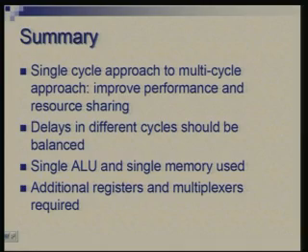So, finally, just to close, we had a design where the data path is conceptually simple in terms of the key resources, just one ALU, one memory and one register file, but there are registers and multiplexers which glue these all together. So, next we will look at the issue of control design for such a data path. Thank you.